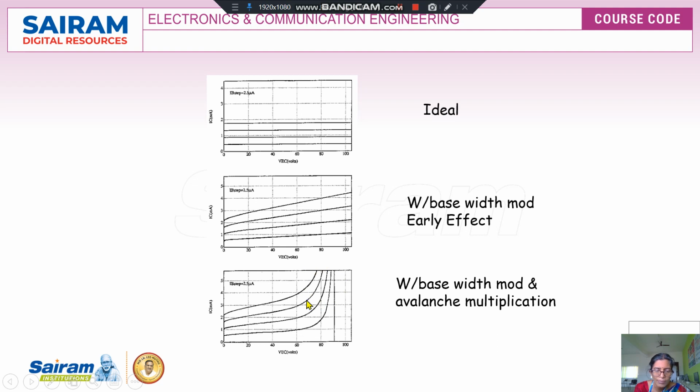There are some transistors, avalanche transistors, which are used on the receiver side in optical communication, which work in this region. Those types of transistors use this breakdown mechanism to improve the current gain, or to improve the efficiency of the device during the reverse biased condition. So in this video, we have discussed avalanche multiplication and avalanche transistor operation in detail. This video completes the topics in the third module.